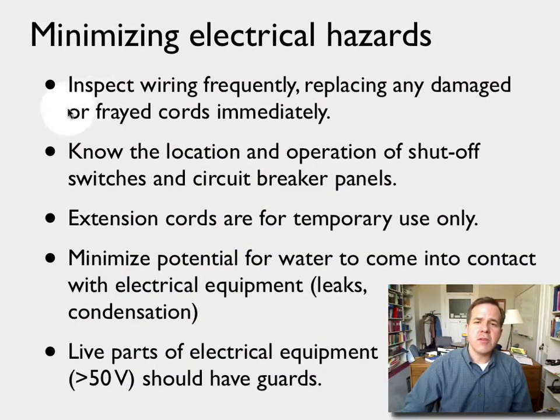Well, the first thing is we inspect wiring on all of our equipment frequently. And if we notice that any wiring is damaged or frayed, those have to be replaced right away. Those are an imminent hazard that need to be paid attention to.